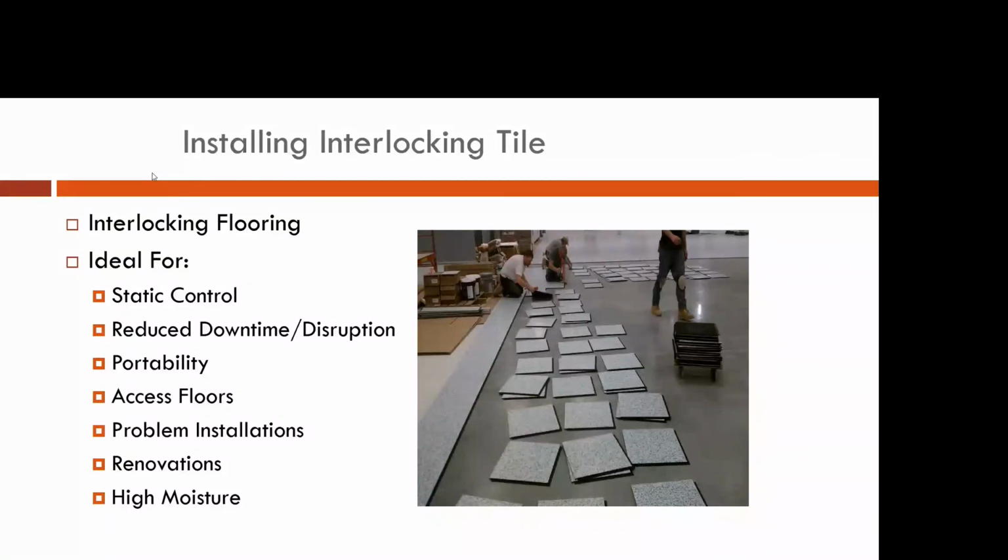And you don't have to move your equipment in and out of the room, because you could build your floor around the equipment. You don't have to put ESD flooring under the equipment, because equipment is generally always grounded, and it isn't a point where the human operators are getting underneath the equipment and standing there and becoming detached and ungrounded. Again, the biggest thing that interlocking floors bring to the table in an ESD setting is that they are portable and can be reconfigured at will.